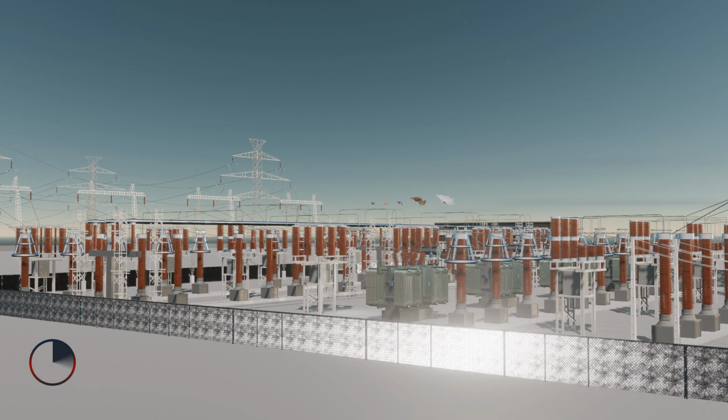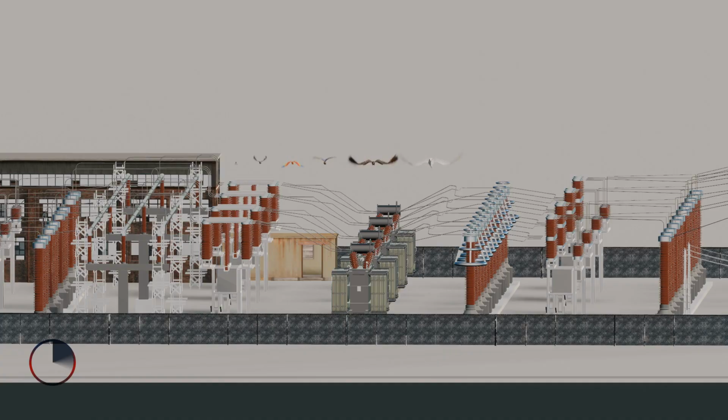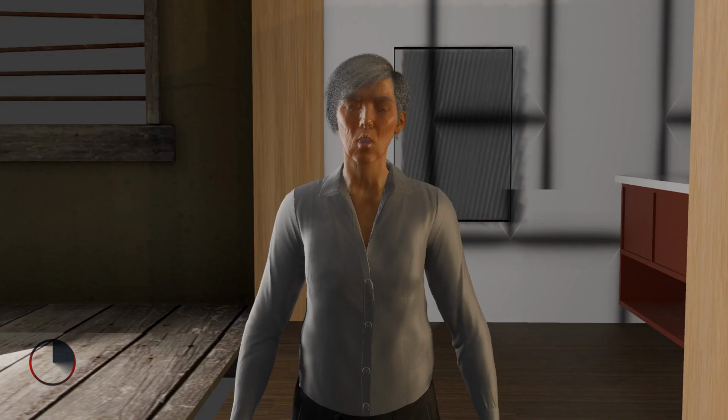And the best way to achieve the required power needed at the receiving end is to increase the sending end voltage. That is, the higher the voltage, the lower the current. And the lower the current, the lower the resistance losses in the conductors. So when resistance losses are low, energy losses are also low. We all know that the consumer end is several kilometers away from the generating station, hence the reason why the voltage is stepped so high.